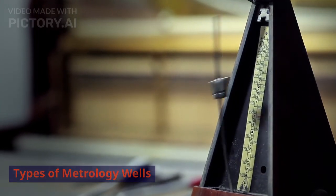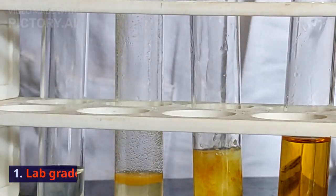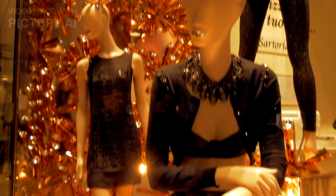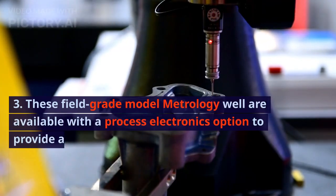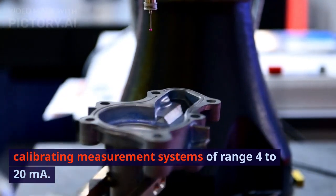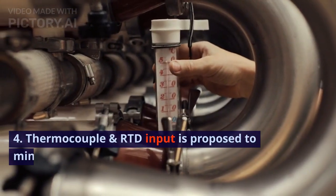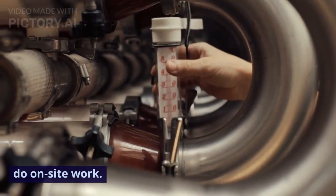Types of metrology wells. Metrology wells are categorized into: 1. Lab-grade models. 2. Field-grade models. 3. These field-grade model metrology wells are available with a process electronics option to provide a 4 to 20 mA loop circuit for testing and calibrating measurement systems of range 4 to 20 mA. 4. Thermocouple and RTD input is provided to minimize the number of instruments needed to do on-site work.